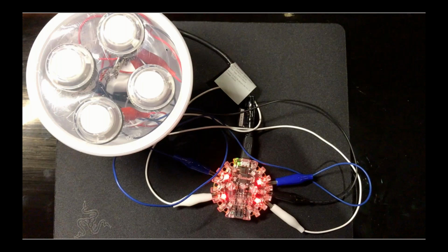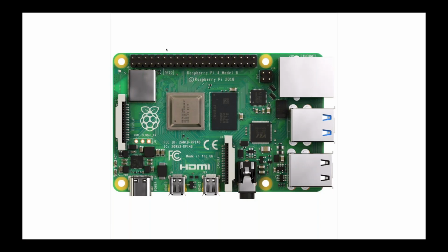To do that, I got something called a Raspberry Pi. A Raspberry Pi is a little computer that's just printed on a circuit board. It's pretty awesome. I recommend playing around with them. The important part about this Raspberry Pi is it has something called the GPIO header. It's up at the top here, in two different rows of pins. GPIO stands for General Purpose Input Output. These are just pins which the Raspberry Pi can use to send electrical signals through.